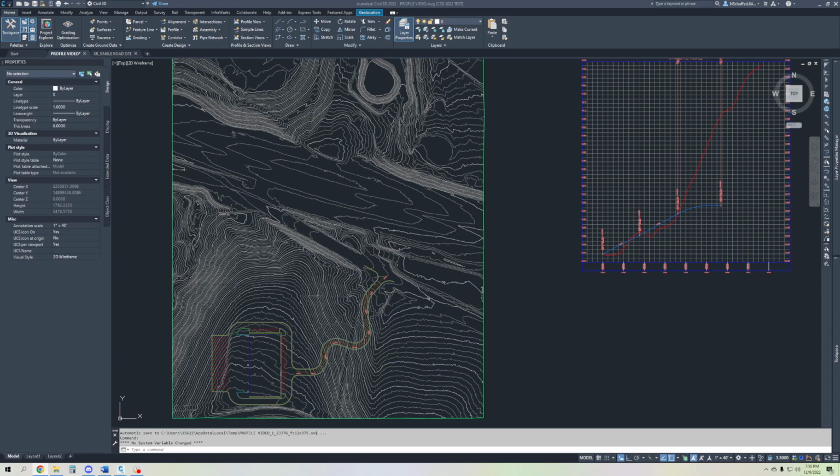What you can end up doing is creating sites for each one of those parcels so that you can add feature lines or grading or corridors or whatever else that you need for each one of those properties, and the sites will keep them separate but also be the same. So you can add the sites, feature lines and grading objects and alignments to one finished grade surface, but they won't interact with each other while you're working on grading.